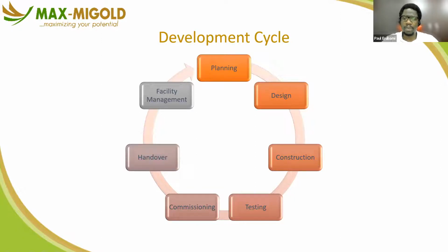During construction, because you'll be making changes or variations, you'll be having things like changes in specifications and quantities, you need to be updating the construction drawings and the bills of quantities, because an output from the construction process is an as-built bill of quantities, just the way you have an as-built set of drawings, which we call the as-built drawings. They have to come out of this. So every time there's a variation, a change in scope, approved by the owner and by the consultants that have been employed, those need to be documented, right?